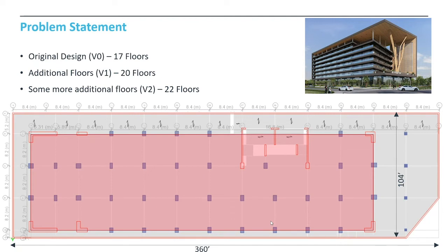So whenever they use the concrete for strengthening or jacketing purposes, we asked them to take the same number of cubes per truck or similar quality checks. And the same thing was for steel also. Since the building is still under construction, the same material supplier provided that steel as well, and the same tests were applied on those steel bars also.